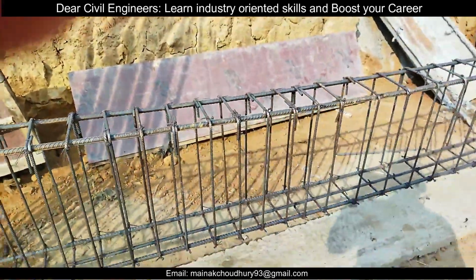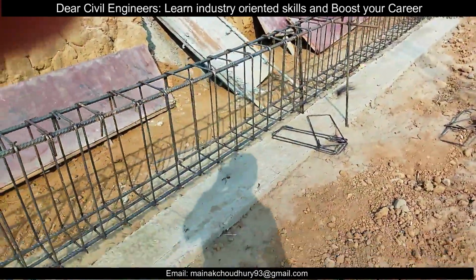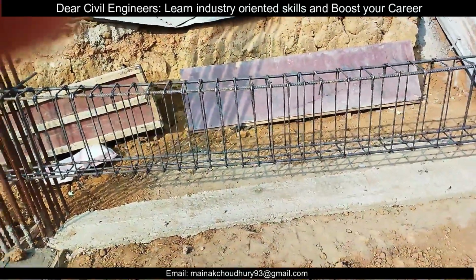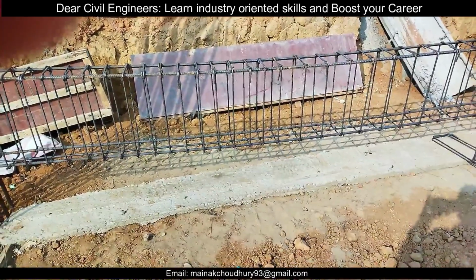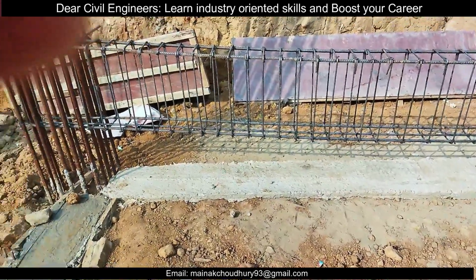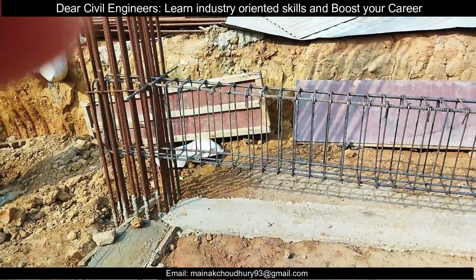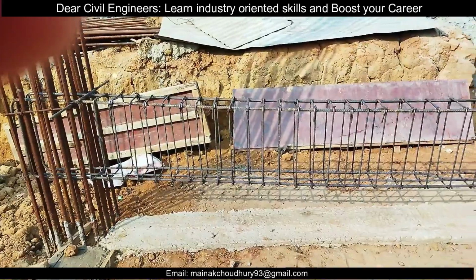Okay. So the next thing which we need to check is the lapping zones. As you can see here, since the extra rebar is not provided, all of the rebars here are the main rebars, and all are through rebars. So here you need to check the lapping length. For the bottom rebar, lapping can be done at the junction here and at a distance of L/4 from the junction.